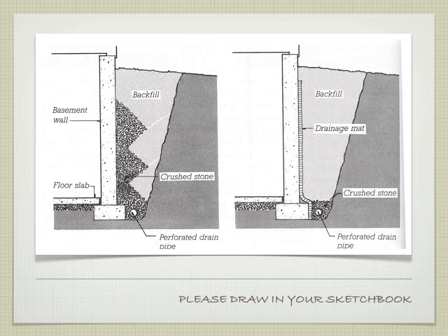And then in this region I would have my backfill. The hatch for a backfill is generally this, on an angle. This is what blueprint reading classes are for. You don't have to know this. I'm just doing it. And if I was doing the hatch for regular dirt, it would be orthogonal, something like that. And so I'll call this backfill.